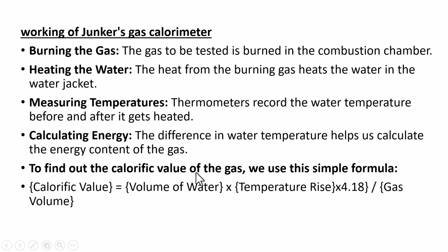To find out the calorific value of the gas, we can use a simple formula. Calorific value of the gaseous fuel is equal to volume of water into temperature rise, that is the change in temperature, into 4.18, divided by gas volume. That will give the calorific value of the fuel.